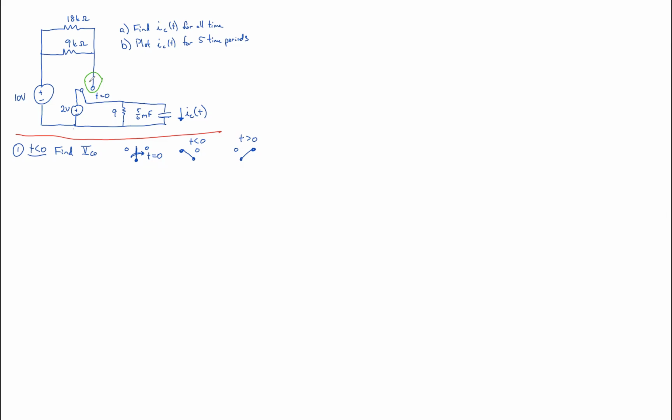And if it contributes no current at all to the circuit we're interested in, we don't need to draw it. We can actually see that there's more stuff that we don't need to draw. If we draw a node around here, we can see that the only wire this node hits is right here. Therefore this wire carries no current.